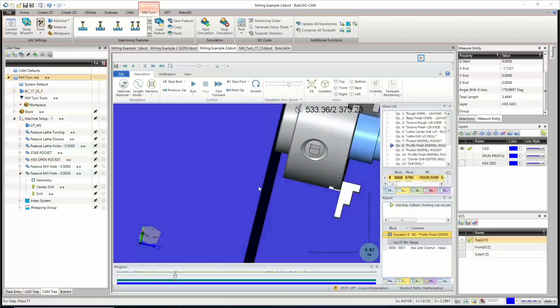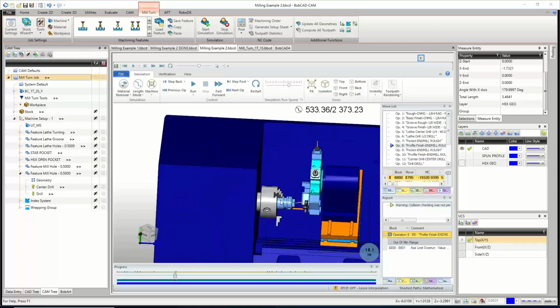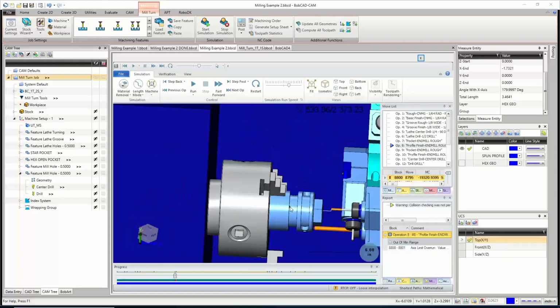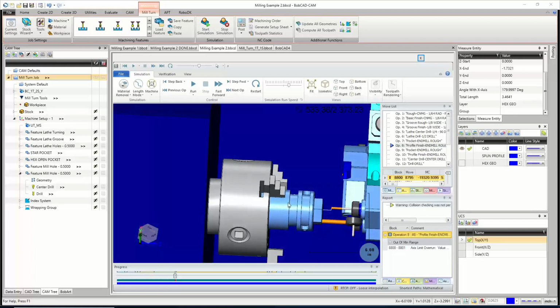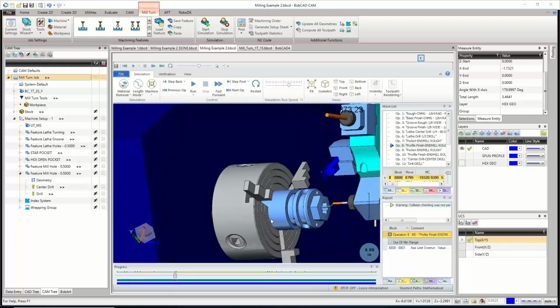But really, all I'm looking at on that now is I want to get kind of square to the front face of this machine here, and then zoom in on it, and just kind of line it up with the jaws. Find out we got a bit of extra material there. So yeah, I don't think we're going to have any collisions when we do that groove this time. We shouldn't have anything going past that. So there we go.